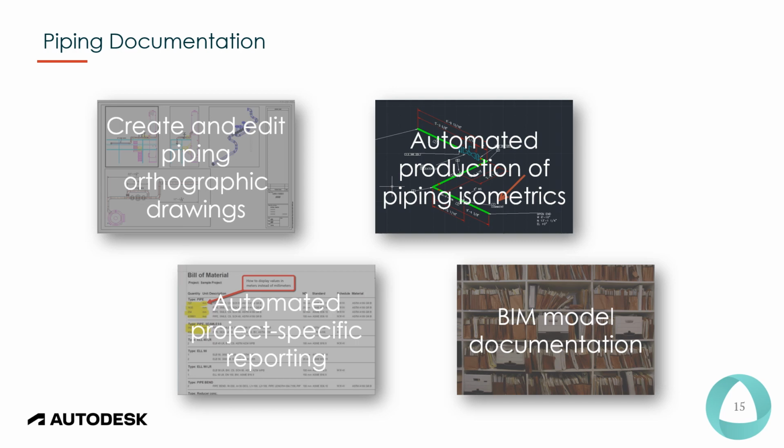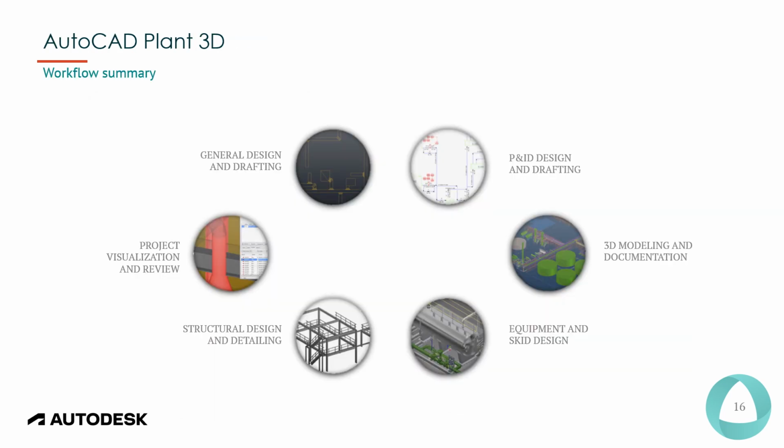For creating piping isometrics, you can create industry standard or project standard piping ISOs directly from your 3D model. You can also create reports, so you can define the report format for the project and then automatically populate this data from your 3D model. Then for the BIM modeling documentation, you can work with other industry disciplines to create the BIM models for the plant.